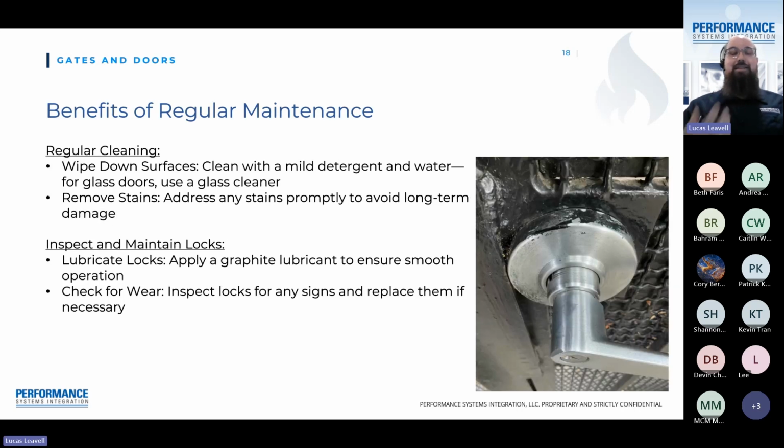Beyond that, cleaning is actually a fairly significant thing that we do with anything that's metal and metal components. We will wipe down and remove accumulated dust and or debris that can lead to corrosion building up. Previously, I showed a picture of the gate or the fence that was corroding at the bottom from the irrigation sprinklers. That's just water stagnant on top of it, building up on top of it and eroding away the enamel protective coating. For all intents and purposes, if they had been maintaining that and cleaning it off regularly and not letting water stand on it, the fence would have lasted a significantly longer amount of time.